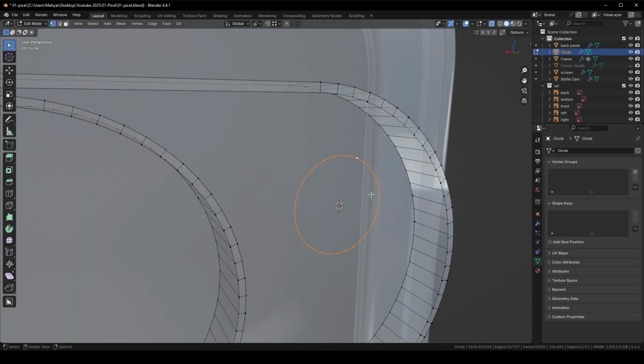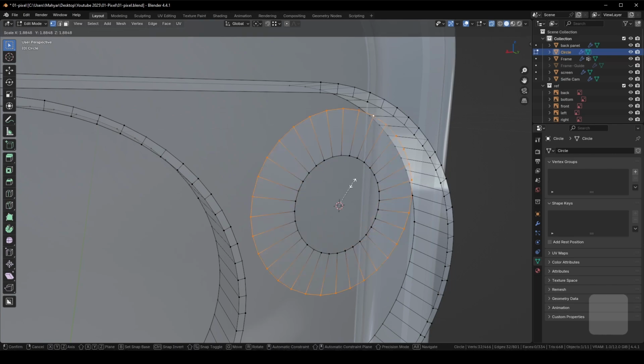Since this is a perfect circle, we can have the edge loop for beveling without needing to create face and inset. We can simply go to bounding box center, press E to extrude, press F. Since it doesn't have any dimension in Y-axis, we don't need to press Shift Y.